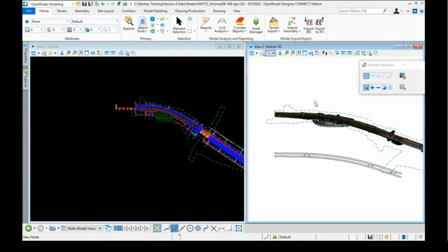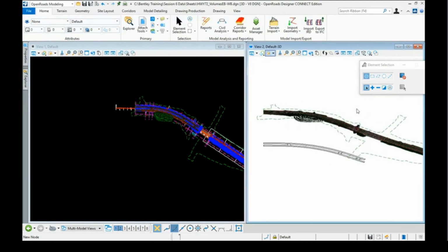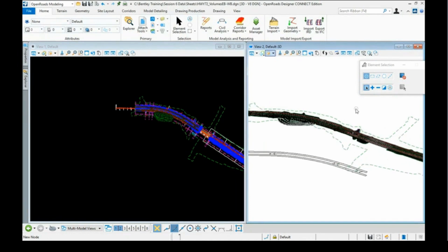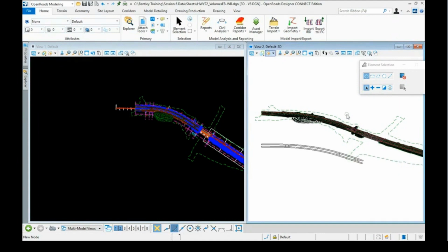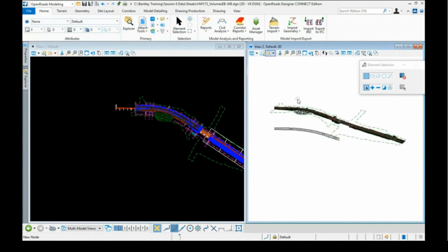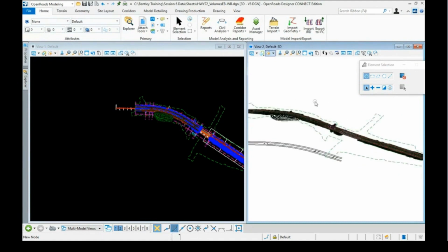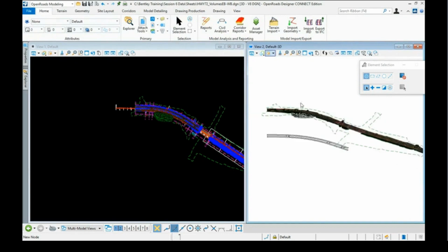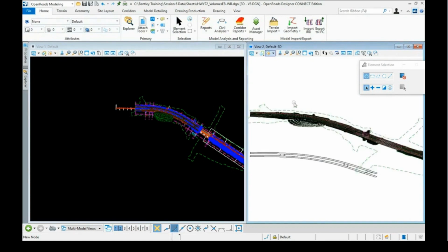So I want to now do some end area volumes. We understand that the best for sure is the 3D prismoidal, but we understand that there are some maybe agencies that are still relying on end area volumes. And maybe we just want to use that as a QA check. It's kind of an old methodology. It's not as precise, but since there's so many people still using it, people like it, we provided the option to do it here. And so let's talk about that method now.